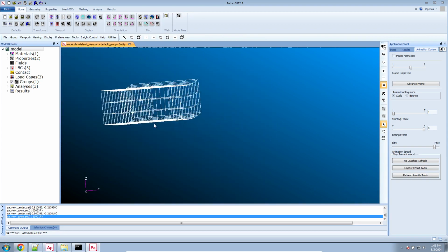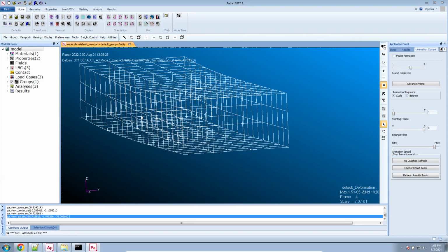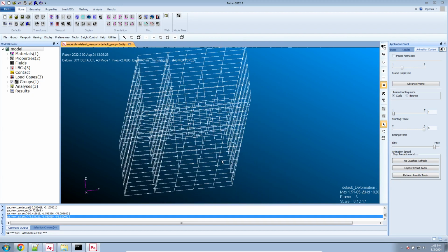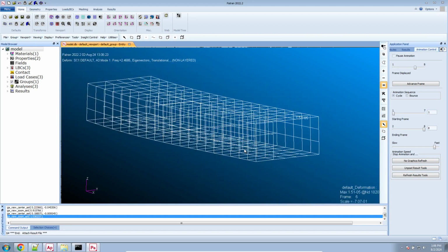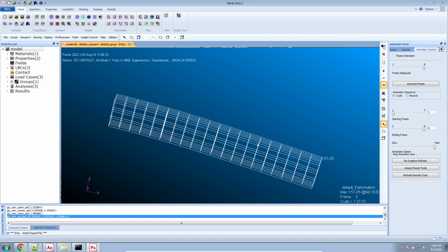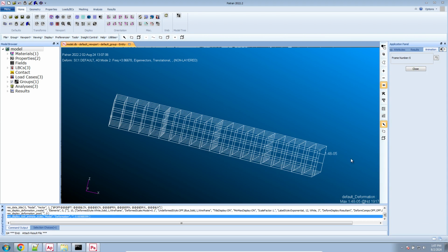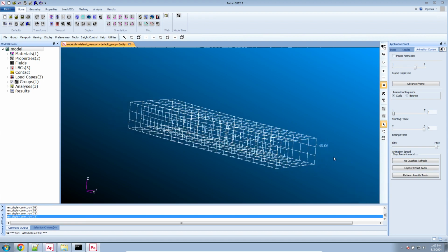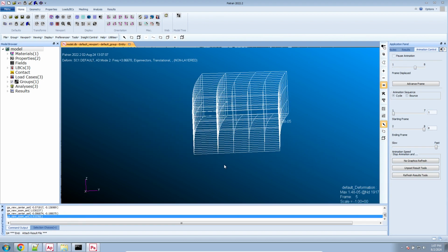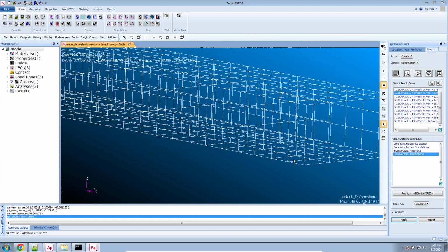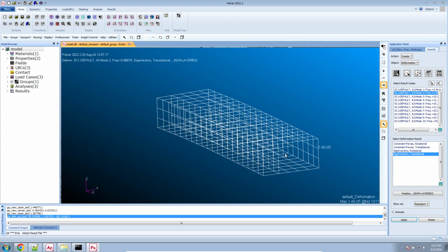And now what do I have? Here is the mode shape of my wing box. Here you can see that the beams are moving along in the eigenvectors. So this is good. This is telling me that this structure is connected properly. Here, let's just go ahead and take a quick look at the second mode shape. And let's go ahead and take a look at the animation. So this is moving horizontally, if you will. And here again, the mesh seems to be connected properly. Okay, perfect. So we're done with the normal modes analysis. Our beams are properly connected to the rest of the mesh.